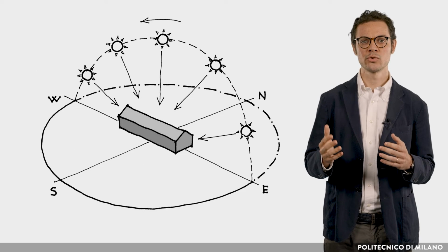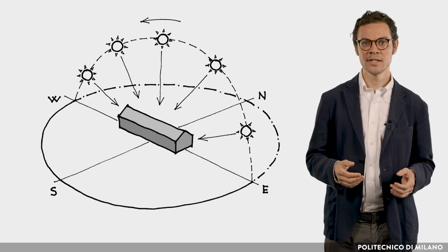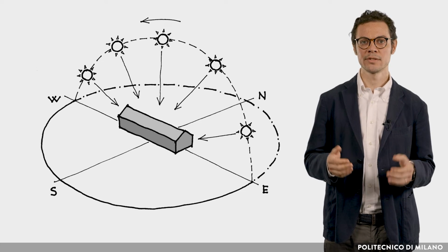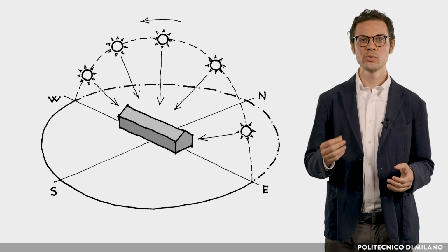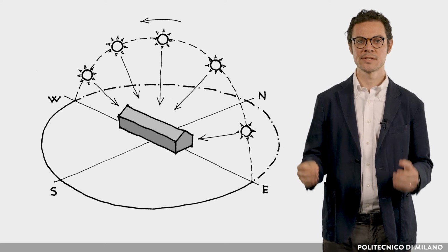In general, buildings in temperate climates can be arranged rather freely. Settlements should be semi-compact to provide mutual shelter from sun in hot season, but also wind protection in the colder one. In this zone, buildings should be preferably compact. The orientation of the building highly affects its energy demand, thus it should be carefully considered. In general, buildings should have an elongated shape along the east-west axis.